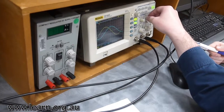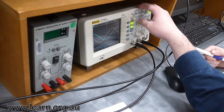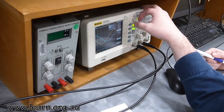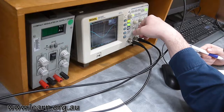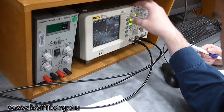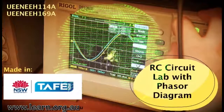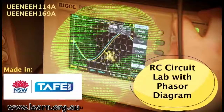Now it just comes down to the students to measure the phase difference on the oscilloscope, and they've been trained how to use the cursors on the oscilloscope to accurately measure that phase difference. Then they'll take that phase difference and do some maths with that to convert it to an angular difference out of 360 degrees. Make sure to see part 2, where we go on to explain this further and draw the phasor diagrams on the board and have a closer look at the oscilloscope to see the time difference between the two waveforms.